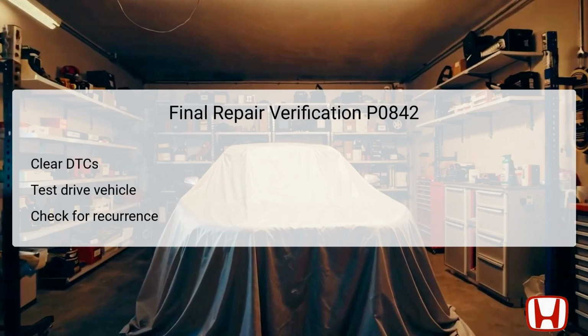After completing repairs related to DTC P0842, it is essential to verify that the repairs were successful. Start this process by clearing any stored DTCs using the Honda Diagnostic System, HDS. Once the codes are cleared, perform a test drive, focusing on the transmission's behavior during shifting and ensuring it operates as intended. During the test drive, the technician should observe for smooth gear transitions and the absence of check engine